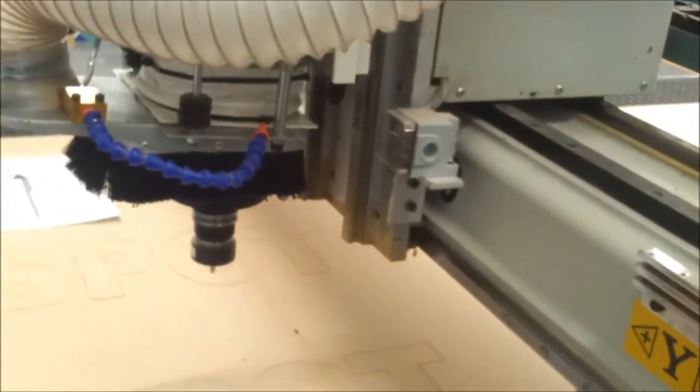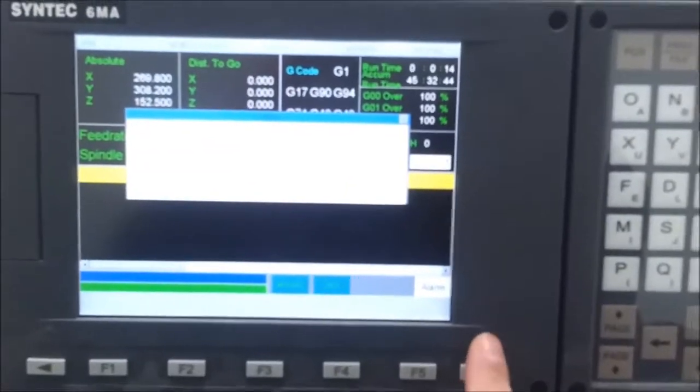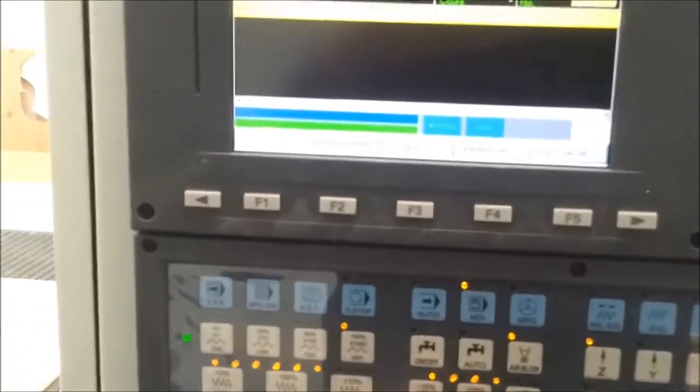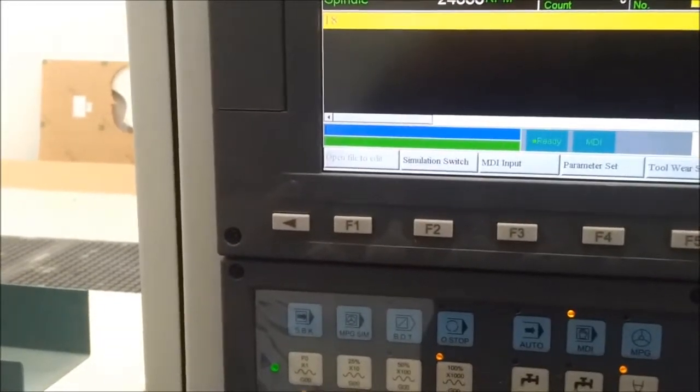Now, being as I already have my automatic tool height reference tool in there, if I just click one of these buttons, to this one over here, to clear it, so it's gone, and then press this, because the F2 is on, it will actually go, and it's still set to T8, it will go back and then check the tool height.